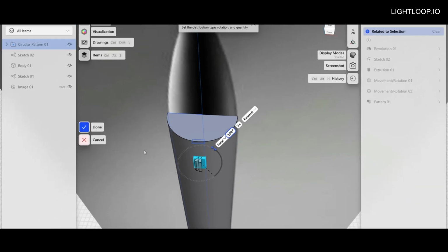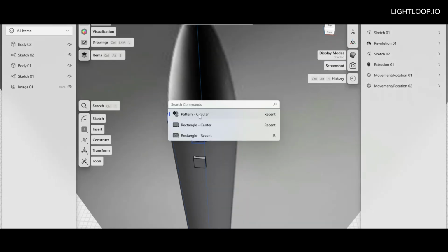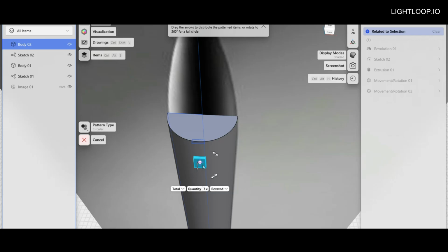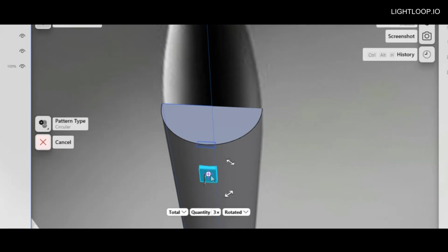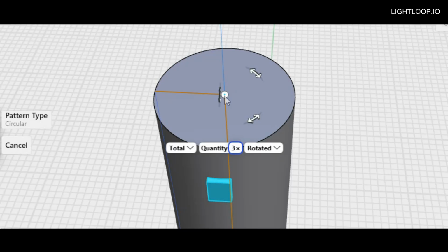And the reason why it's doing that is because its center is rotating around its own center point, which is represented by this white dot right here. So it's just rotating around this point. So in order for us to rotate the body around the center of the rocket body instead, we need to grab this white dot here and we just need to place it in the middle of our rocket, not the small body that we just created over here.